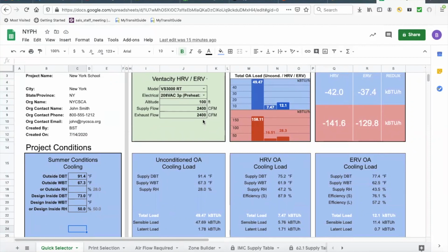For many years, it's probably 10 to 12 years now I've been doing this, when we talk to people about installing ventilation systems, we don't like to just install a system that's operating to meet your minimum requirements for ventilation at capacity. In other words, a 3000 CFM unit, I don't want to put that on the roof if you need 3000 CFM or even 2900 CFM.